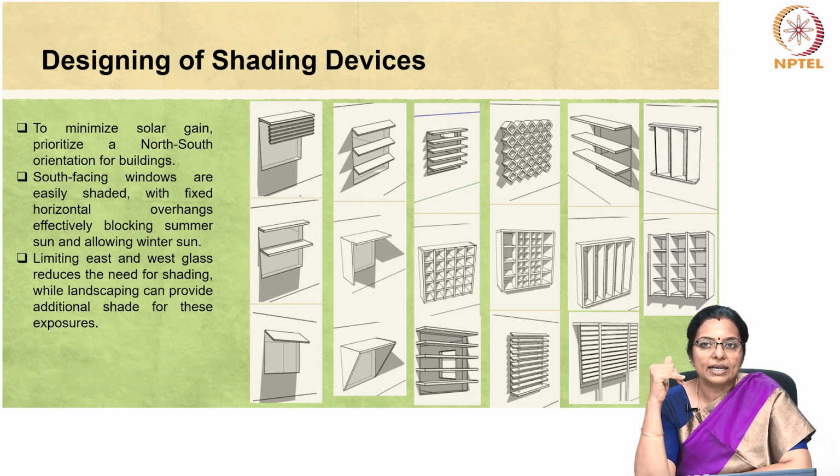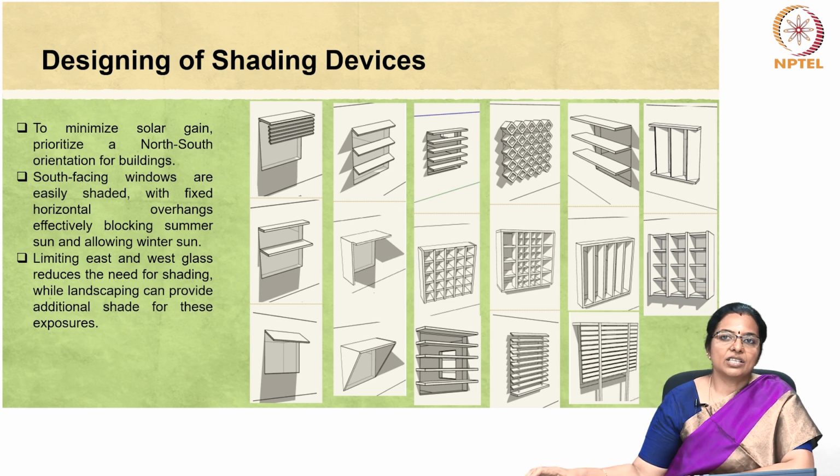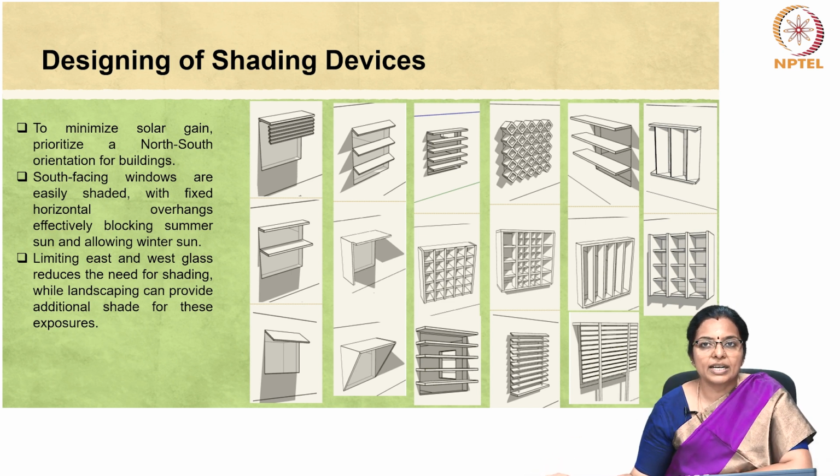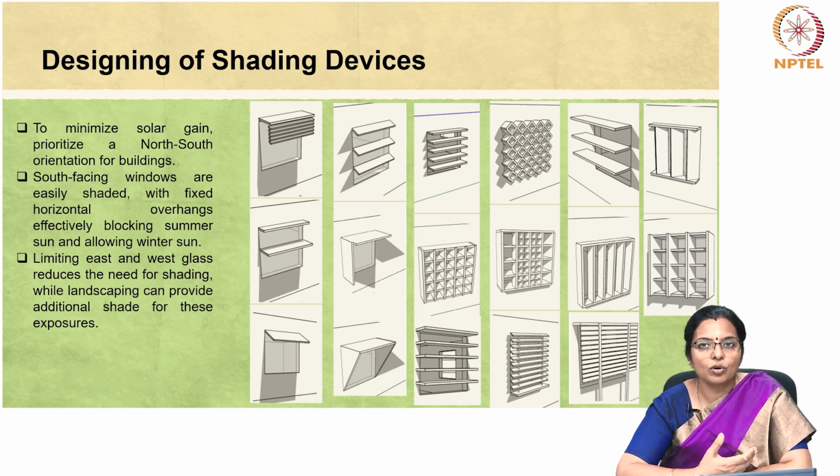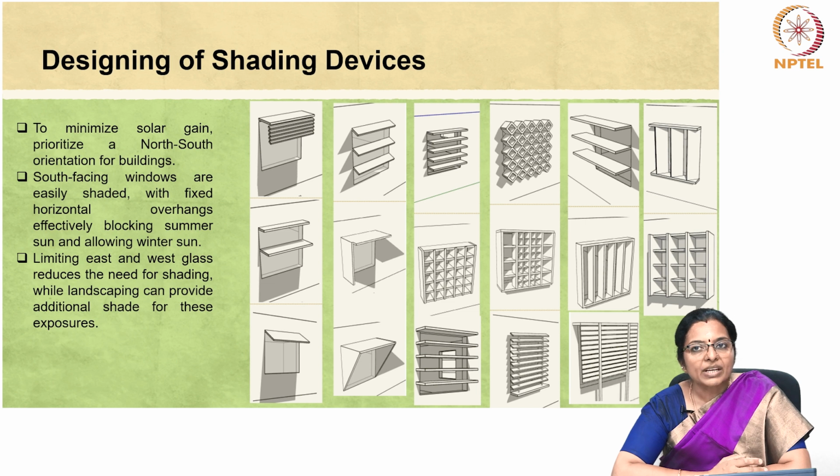On lower buildings, well placed deciduous trees on the east and west will reduce summer overheating while permitting desirable winter solar gains in the cold part of the country. Semi outdoor spaces such as balconies can provide shade to the glazing or windows on the lower part of the building. And these can be even up to 2.5 meters in depth.